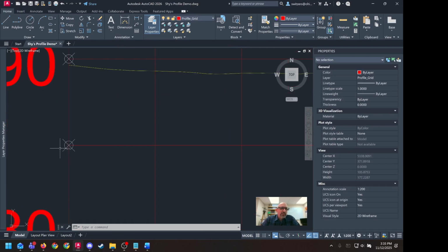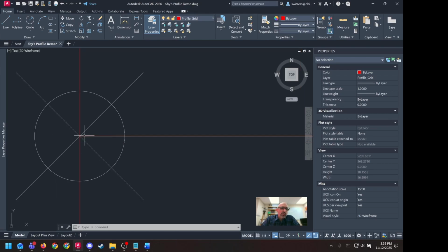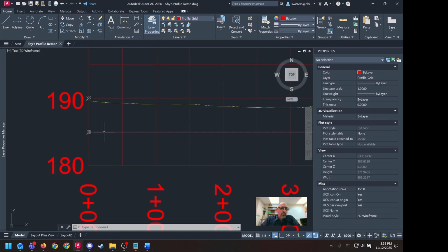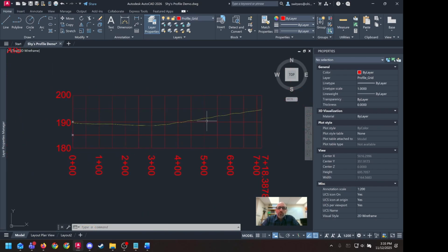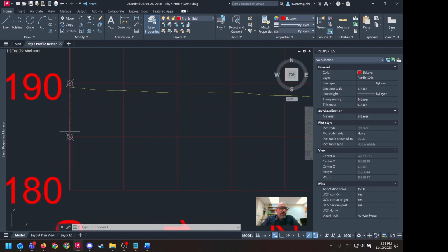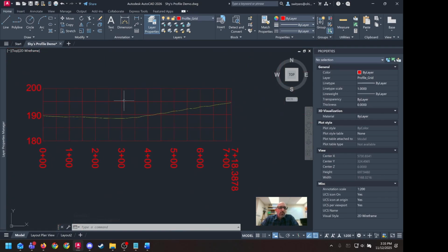And if I did this correctly, again, this is a great way to validate your scale correctly to the correct Y value, is that this 185 I inserted is right here on the 185 value. So that's perfect. So now I have my profile inserted in the grid. I can go ahead and get rid of these. Don't need these anymore. So now we have a completed profile for this roadway.